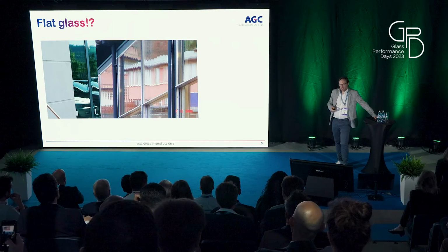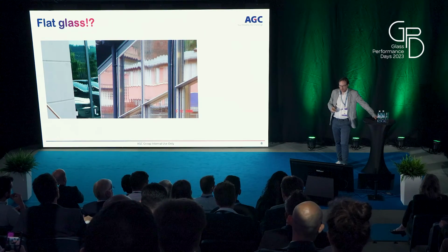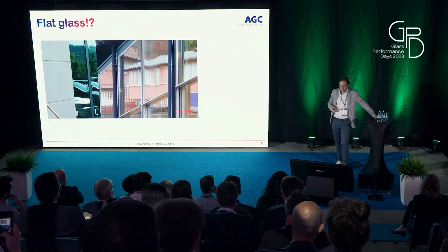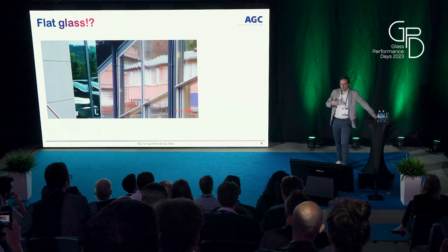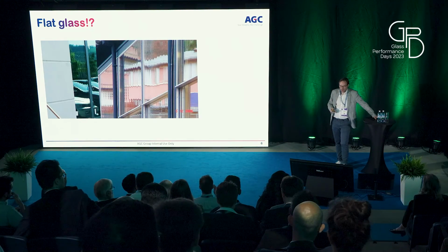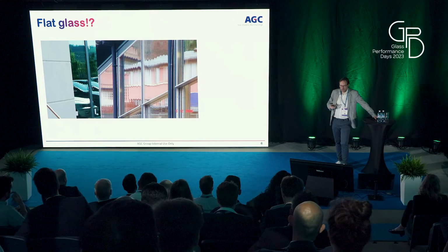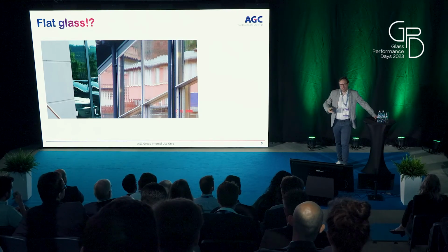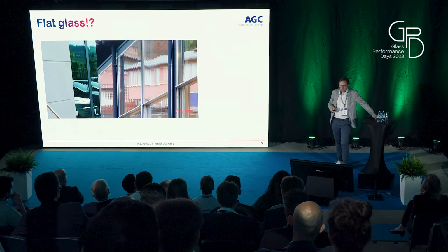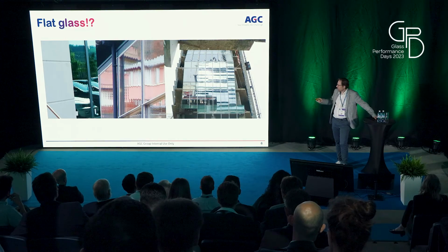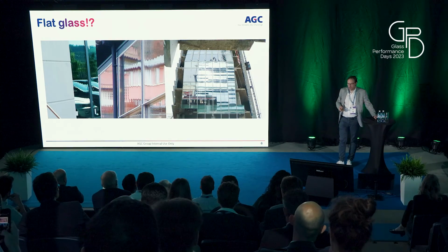And what is the extent of these flatness tolerances? We must normally make samples. You must make physical samples to show it to customers, and how to visualize this in real life. What does it mean to have a certain distortion value? But we have also other types of distortions, like the climatic effect of insulating glass units, which we didn't address here in this study.